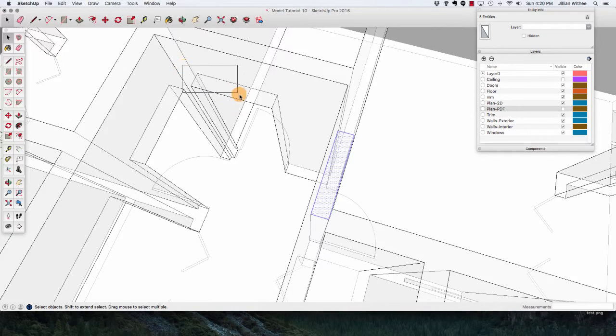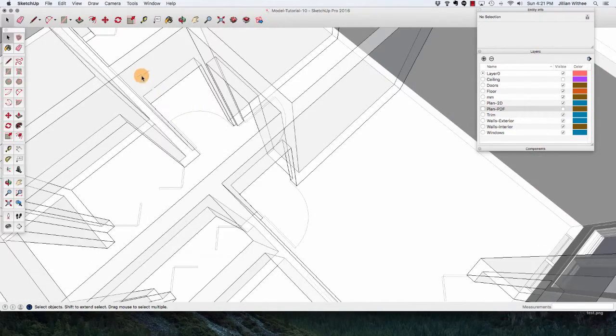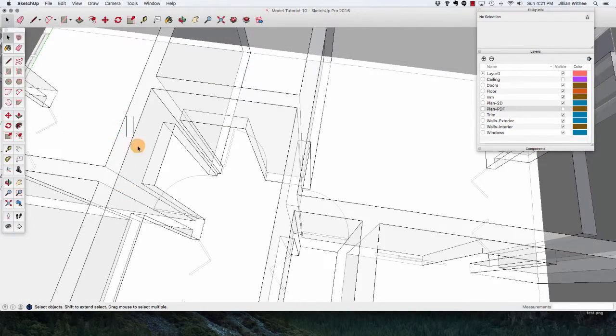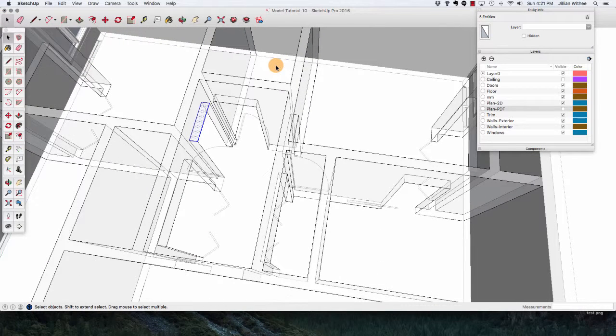So using the selection tool, I'm dragging a box from left to right over that face. So I just select that face and its edges. And I'm using the move tool and dragging it up on the blue axis 1 inch. Let me get my last one here. Sometimes it's difficult to find a way that you can draw the box over just what you want to select. And there's that one. So now I have adjusted all of my door openings.